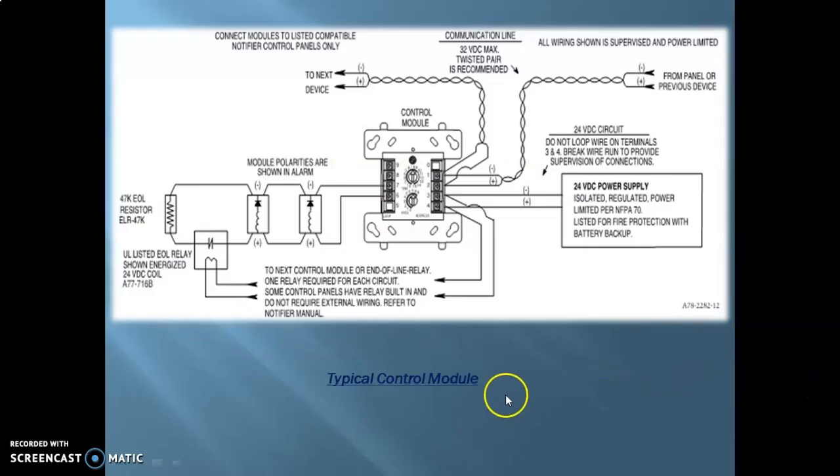So here, as you can see, this is the typical control module that is being shown over here. Again you have the SLC from the previous panel or previous device. The wiring will come into the device, and then from the same connection itself, it will go to the next device in the SLC.